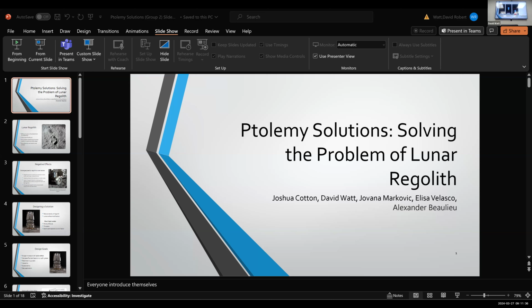If this is a system that you can make work with the deployment of the tarp, this may be something where you say, on an EVA, go pick those up, and either stash them far enough away from the landing site that you're not worried about them being kicked up by the plume, or bring them back into the vehicle because they're reusable. Although that's extra mass you have to bring back to Earth, and you probably don't care about that. But the expectation, I think, would be that your astronauts would do something to mitigate that risk.